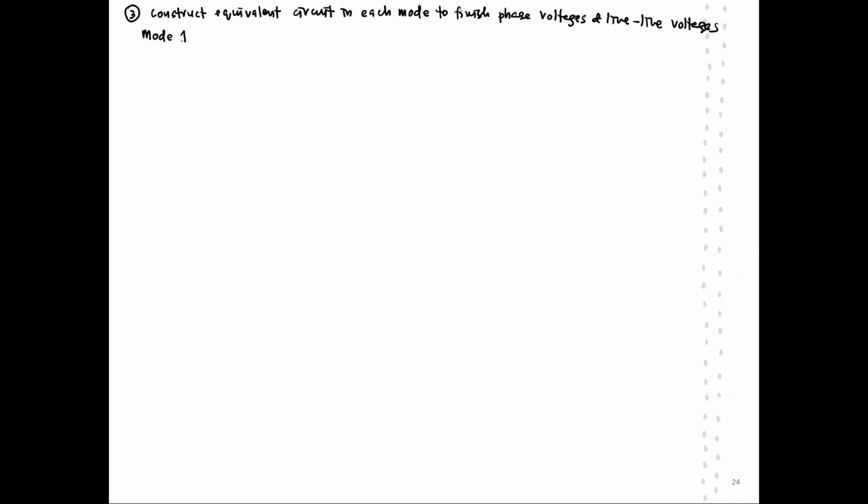We have S1 and S6 here. In order for us to draw the equivalent circuit, you need to make sure where S1 is positioned, in which phase. Is it the upper switch or the bottom switch? And as well as S6. Like I mentioned in the previous class, this is the position of the switches: S1 and S4 are for phase A, S3 and S6 are for phase B, and S5 and S2 are for phase C. So S1, 3, 5 are called upper switches, and S4, 6 and 2, the even numbers, are called bottom switches.